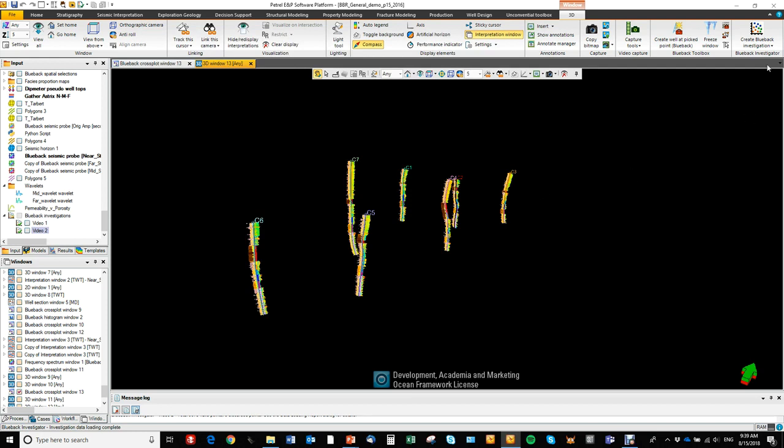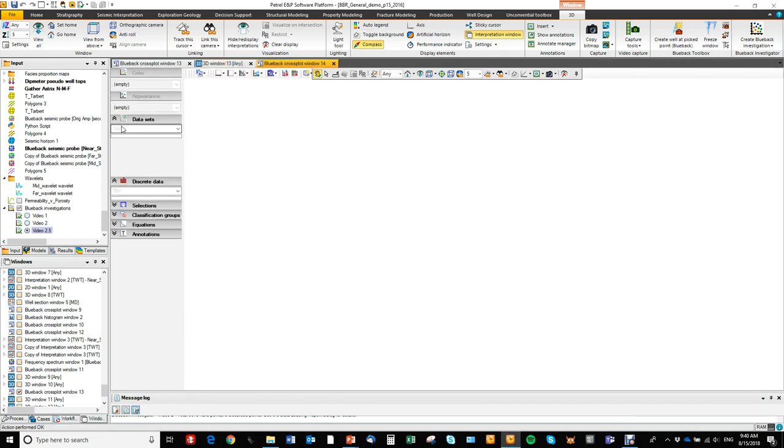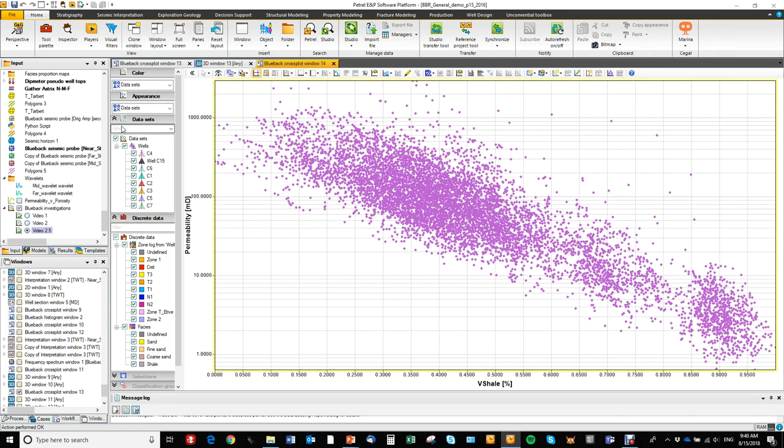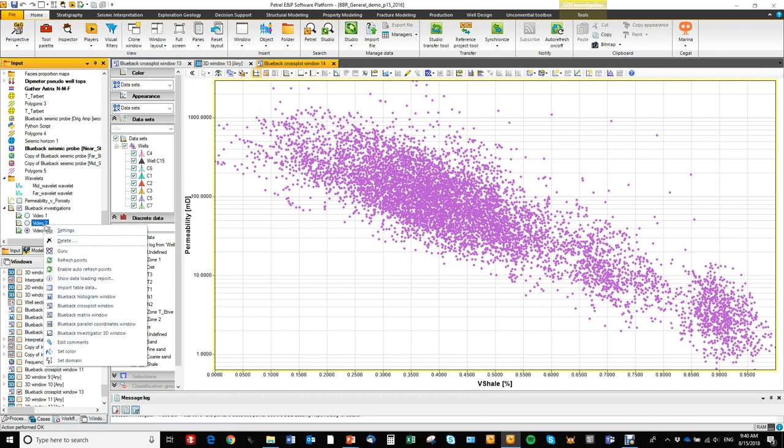Let's just have a look at the direct plotting options. So let's say we want to build this investigation and plot it directly. We can build the investigation and plot that investigation directly in a cross-plot window. Again, it prompts for a name, because now we're actually building the identical investigation one more time, and that's not practical, but that was just for demoing purposes. So now we're building this investigation and plotting it directly in one of the windows. But ideally you would just build the investigation once using the ribbons buttons and then do the plotting directly from that investigation.